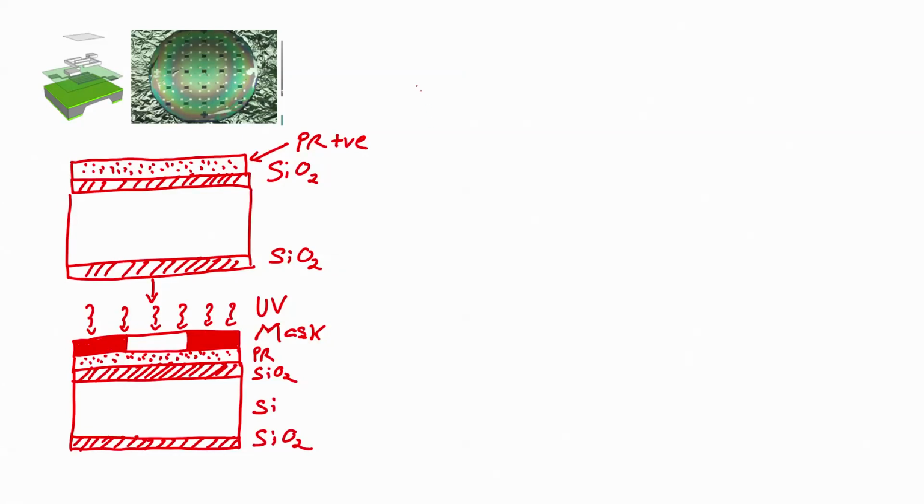What is the next step? Of course, when I say we are spin coating positive photoresist, it should be assumed that after spin coating we will go for soft bake, right. After positive photoresist we have to go for soft bake. I am assuming you now know it, which is why I am not writing it, okay. 90 degree centigrade, 1 minute, we know it, right.